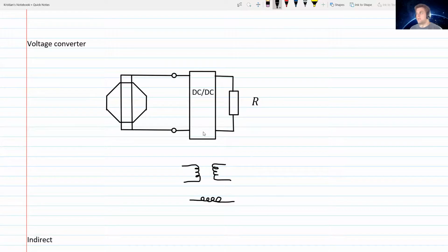Now that we've got the DC converter in place, we need to be able to change the voltage across the photovoltaic cell so that it's always at the maximum power. To do this, we introduce an input D to the converter. Now this input will be required to change as the power changes from the photovoltaic cell. We remember that the irradiance and the temperature will change with the IV curve, and this also changes the peak operating voltage. So this will require methods to